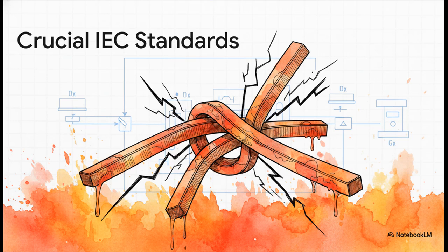To tame those massive fault currents, engineers rely on some very strict IEC frameworks to verify that the theoretical diagram can actually survive brutal reality. IEC 60909 is what calculates just how massive that fault current will be. Then IEC 61439 and 60865-1 step in to make sure the physical copper conductors won't literally bend, melt, or just rip apart from the sheer electrodynamic stress.